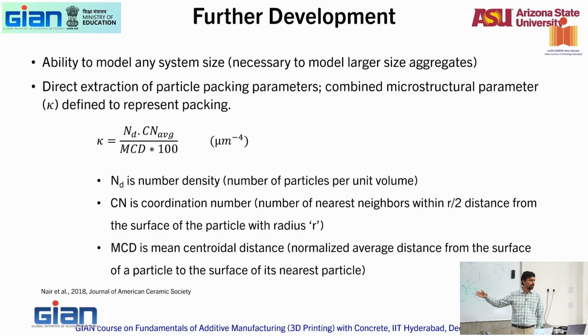It's that important. It governs the yield stress, it governs viscosity, and for UHPCs it governs the strength that you can gain. With this microstructure packing being better, we could end up getting the UHPC strength to 160, 180, and all those things. So this goes into the packing model as defining the microstructure, even defining it in terms of 3D printing.